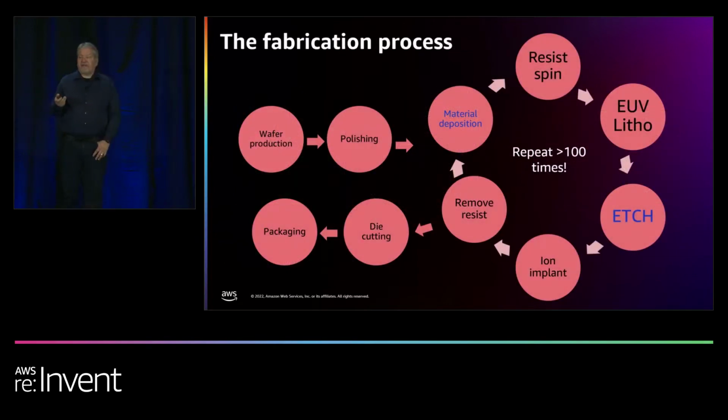The chip making process is actually very complex. It involves 10 or more steps that are similar to old style photography in how they work. We use a special grating called a mask, and we basically shine light through this mask onto the coated wafer to make a picture of a layer of the circuitry. We do this over and over again to make the layers that a silicon device is made out of. Some modern silicon devices can actually have over 100 different layers. And this is a very energy and